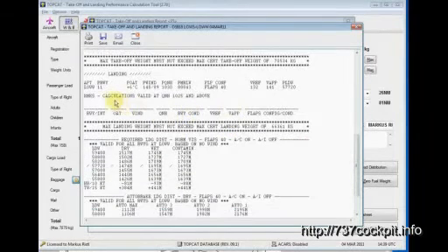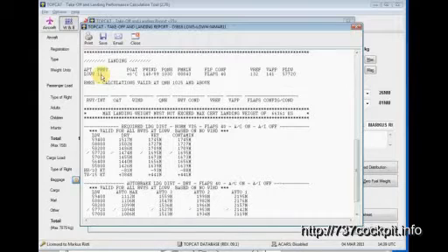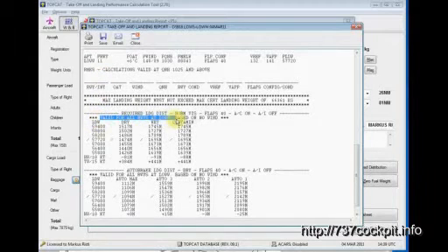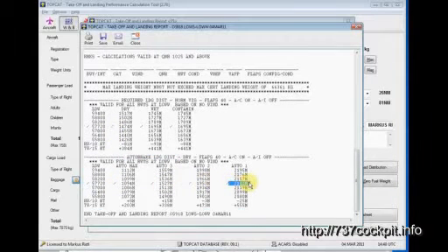Below we have the landing configuration, landing runway 11 here. This is valid for all runways in Vienna based on no winds. So we would have a calculated landing weight of 57.7 tons for a dry runway. If we land with auto brake 1, we would need 2,142 meters. With auto brake 2, 1,953. With auto brake 3, 1,527 meters. And with auto brake maximum, we would have a landing distance need of nearly 1,000 meters.